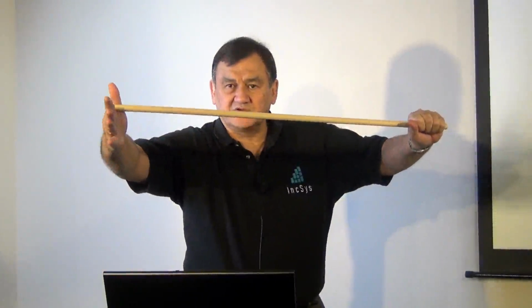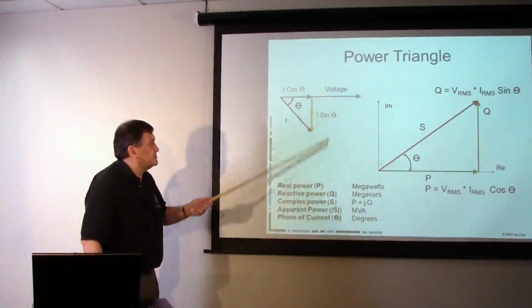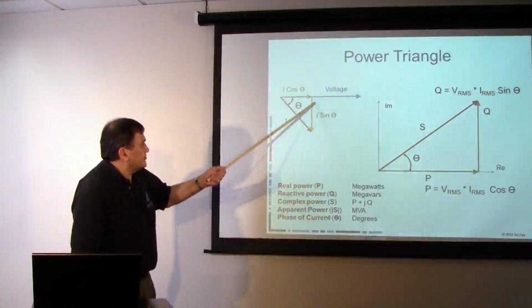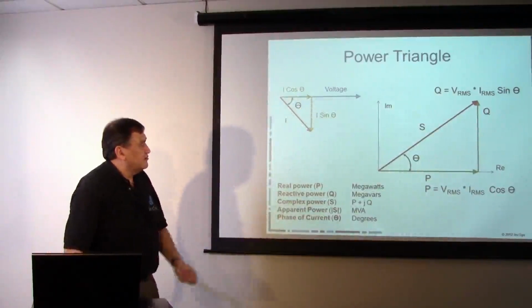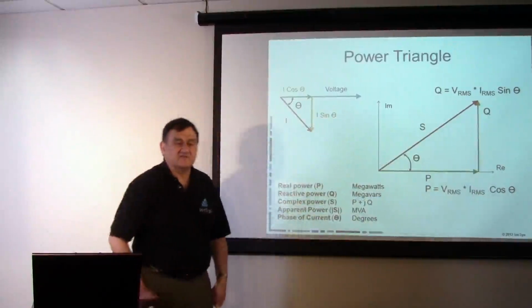When we have a generator feeding an inductive load, we call that positive power. And in the vector diagram, we like to represent positive power as things going up in a northerly direction. So there's actually a little transformation, as whereas my current was leading in this direction, we actually transform that into a positive power going up in a northerly direction.